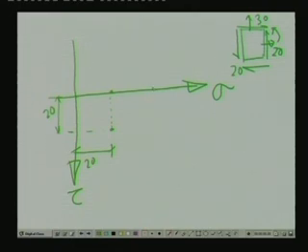So, we represent sigma y and then tau as negative. Tau is negative because the shearing stress on this plane is causing a rotation which is clockwise in nature, which is opposite to the one which we have considered earlier. So, this is negative tau. So, this is sigma y and this is tau xy.